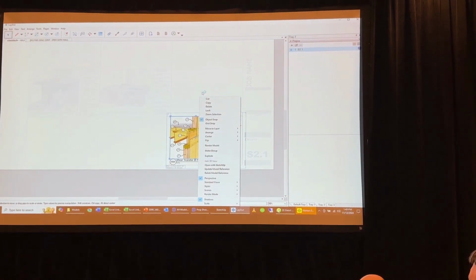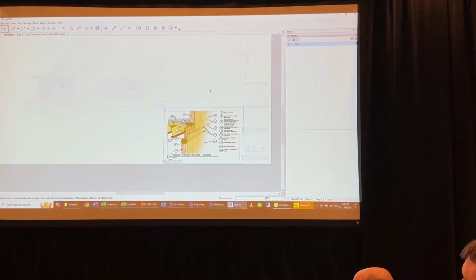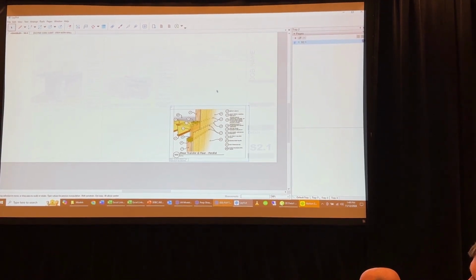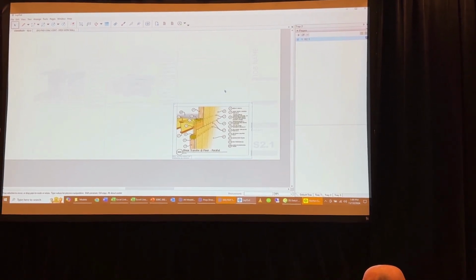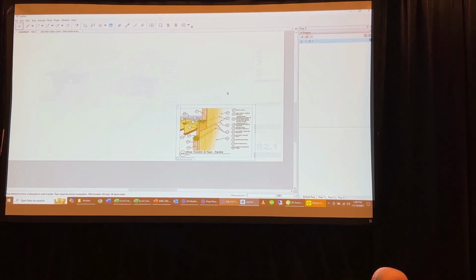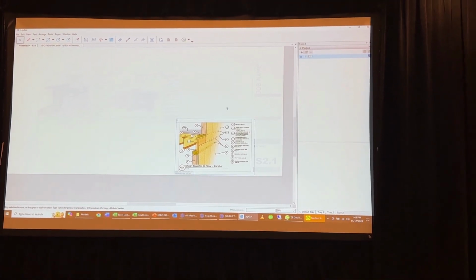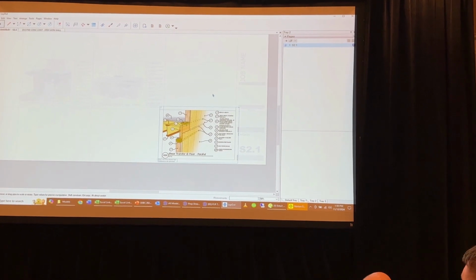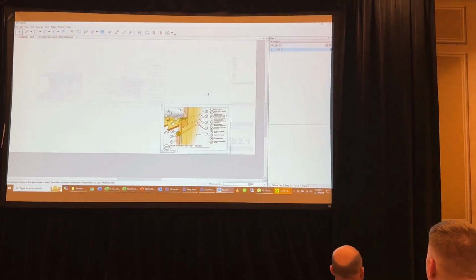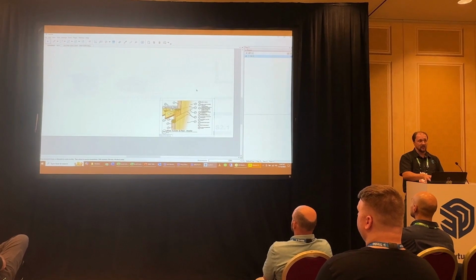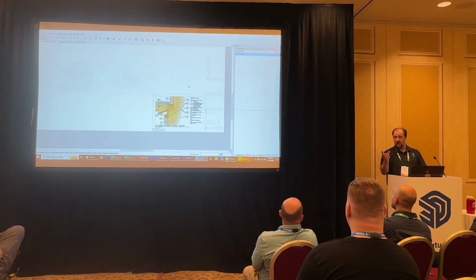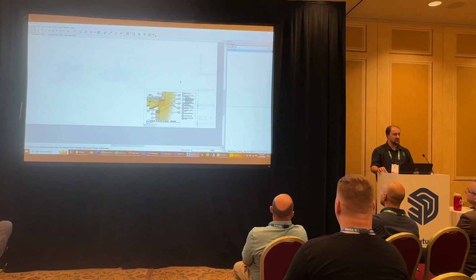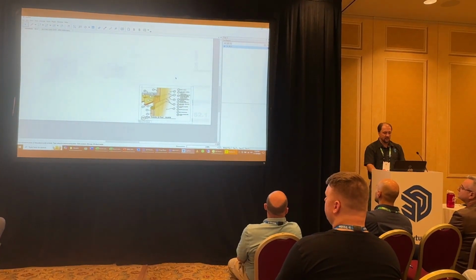So by opening it in SketchUp through here, are you potentially altering your existing life? If I save, and not if you're one step ahead of me. So yeah, that's a very good point. For those that have not run across this, if I go in and alter an existing detail in SketchUp and I save that, it's going to then update all those details in all of the prior projects, which is why we save as details, right? If you're doing a project-specific detail.